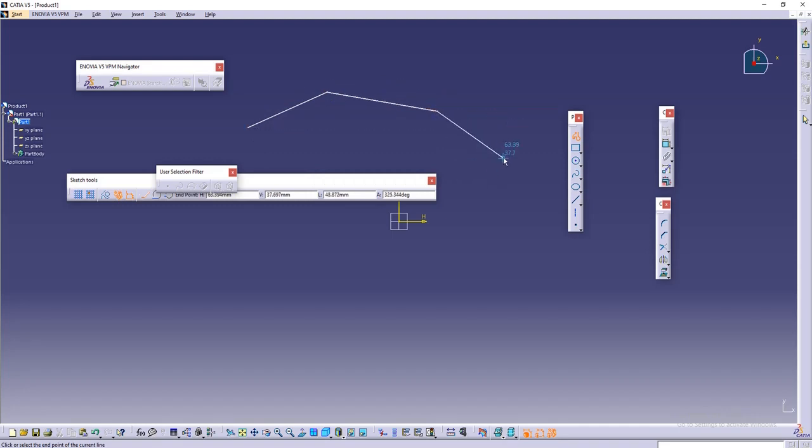Whenever I drag and then click, it will start generating the line, click, click, click, right. And it will also show some dimensions, but you cannot directly change the dimensions from here, you need to use the dimension tool. Like in Fusion, you can directly change the dimension, that is the difference. So this is like that.